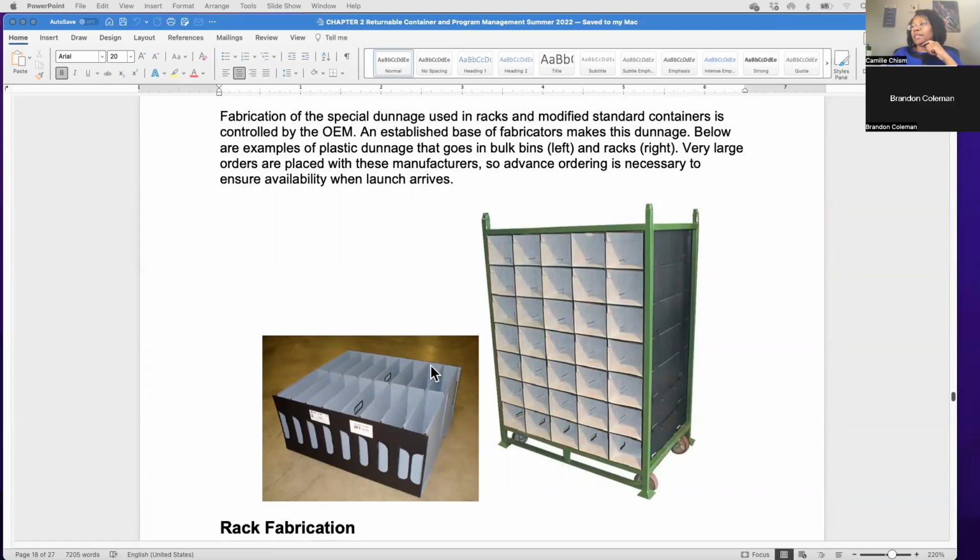This has lining on it that would protect probably some sort of Class A surface, but then also separates them. So if you have something like a door handle that is plastic on one side, that's a Class A surface that consumers will see, but then on the inside you have clips, because that is how they install that part into the door frame. The metal clip might scratch the Class A surface. So that's where you might see this sort of divider.